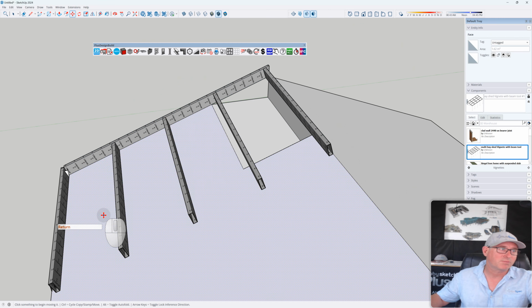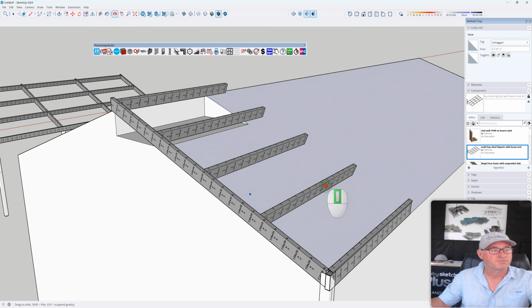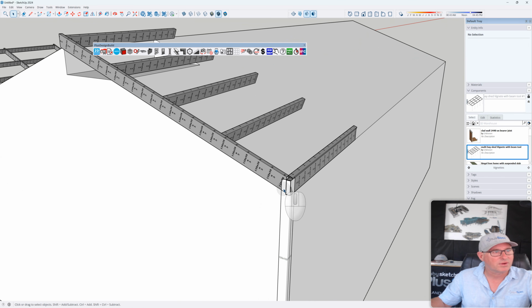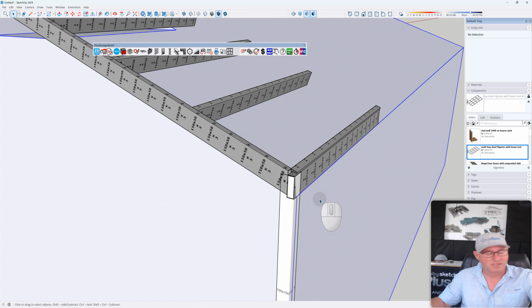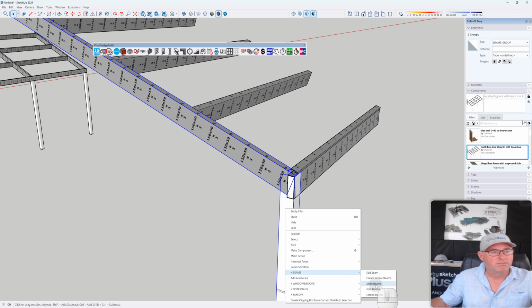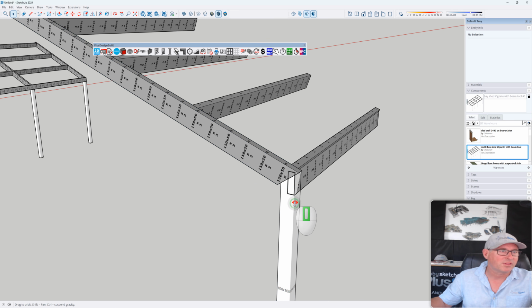Therefore I have equally spaced beams there according to whatever it is I need. Now, I could also miter posts and so on. I'll just show you how that works. I'll just hide this for a second. Hide, use a keyboard shortcut for that again. If I select these two, right click, Beams, Miter Beams, and therefore I've mitered the post.